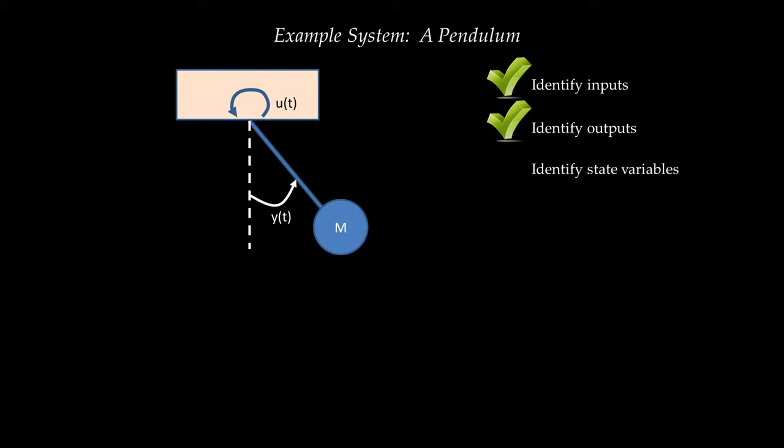Now this is a rotational mechanical system. It stores energy due to the rotation of the pendulum, and it stores two distinct kinds of energy. First of all, as the mass of the pendulum rotates, it rises upwards, and therefore it stores potential energy. Secondly, as the mass moves, it stores kinetic energy. In this particular case, the potential energy is a function of the angle of the pendulum relative to the vertical, and the kinetic energy is a function of the angular velocity of the pendulum.